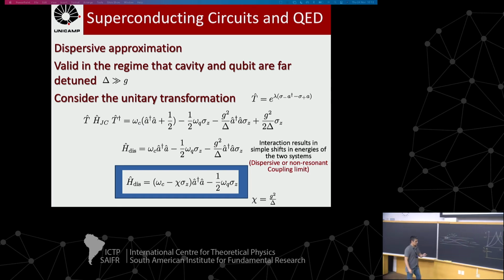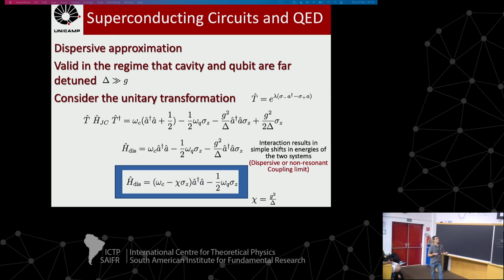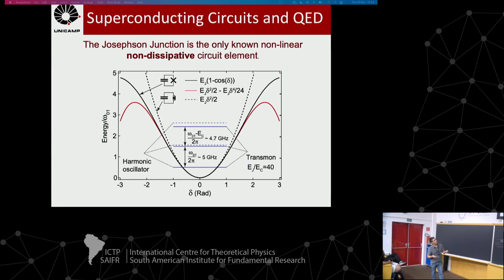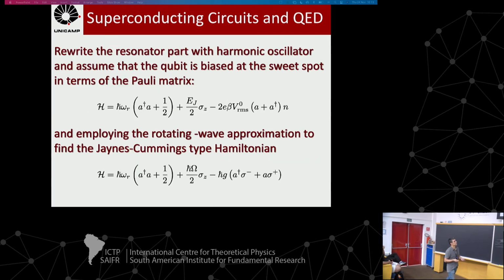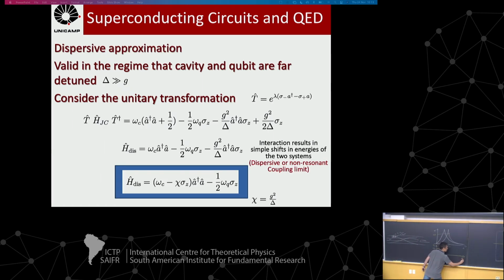Then I start to excite the qubit. I try to send a signal to excite the qubit to see if I can induce the transition I have in the qubit. When we saw there, the transition here was around 5 gigahertz. So here I put frequency. I'm going to probe the qubit. I start here, for example, at 4.9, going to 5.1, and 5 is here.